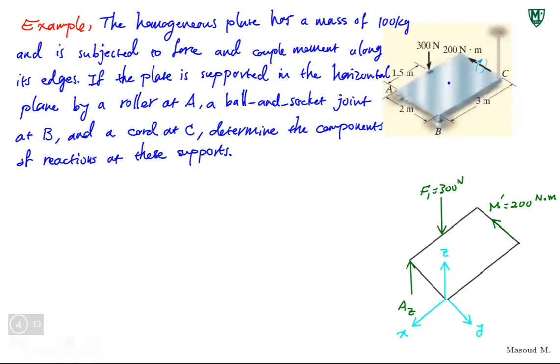Now, actually, I have a roller still here from the last time. If it's a roller, it can go in this direction, and the contact point with the surface would be horizontal, in Z direction in this case, upward, perpendicular to the surface. But if there is friction, then the friction is also preventing it from moving in the other direction, so we had to put another component. I spent 2 minutes explaining just what you said, Richard. I could just say yes, and it would have been understood. Yes, we would have needed an extra component there.